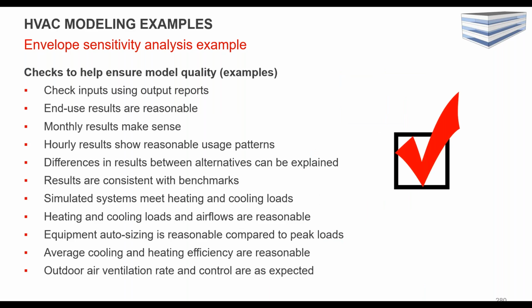And then what are the sort of things that you would look at if you were doing QC? And we'll talk about quality control quite a bit today as well. Look at your inputs, again, keeping track of all your inputs, check those against your outputs that are coming out of the model and make sure they're the same. A lot of times you might see some translation errors, so it's a good place to look for that when you've potentially input something incorrectly. Always looking at the results, making sure they're reasonable and in line with what you expect.